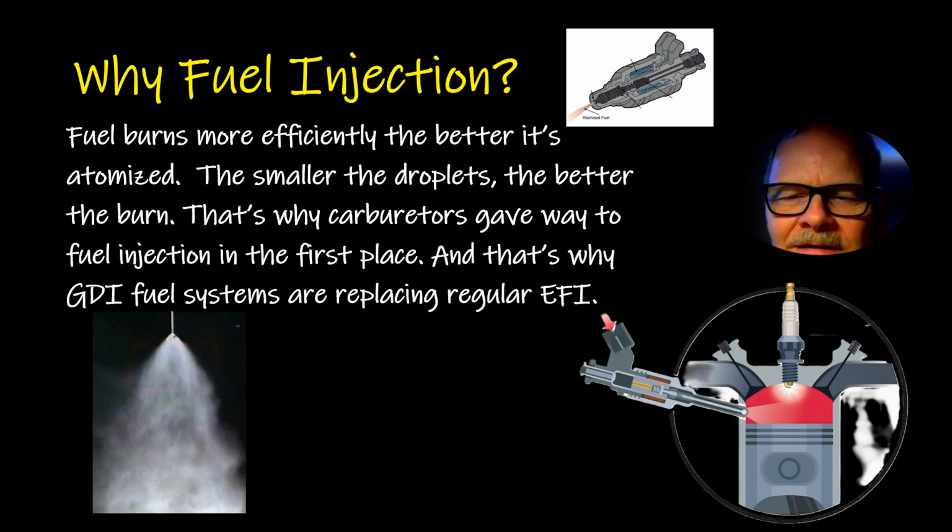If you've got a gasoline direct injection engine and you just putter around town on it, it's going to build up carbon on those valves. You're going to have a mess. It's got to be cleaned up. Now, if you drive it pretty aggressively, you don't typically seem to have as much trouble with the carbon building up on the valves as you do if Granny's just going to the store and back. Of course, that causes other problems too.